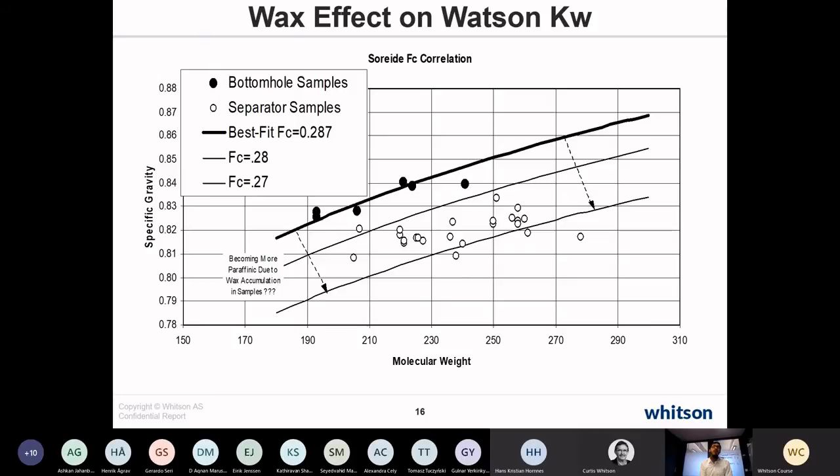You will have two phases in your bottle: a carryover liquid and an equilibrium separator gas. That should be the right separator gas. But if you heat that container up, then some of the carryover liquid will vaporize into the gas phase, and then when you measure the separator gas composition, that will not be representative of the true separator gas you have.